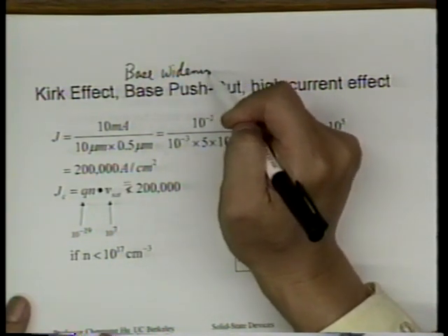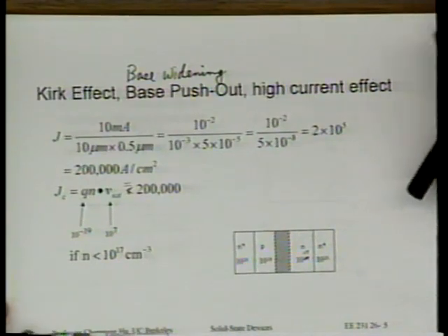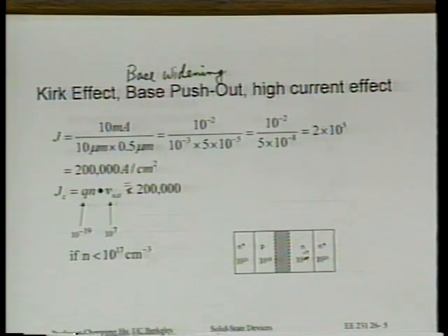And this is the thing that stands in the way between us and the 100 gigahertz bipolar transistor. Actually, the best silicon germanium transistor has an FT very close to that, maybe 90 gigahertz or something like that, but you cannot use it for 90 gigahertz application. Of course, you cannot design all the way to FT. So if we did not have this problem, we could have 300 gigahertz transistor just by pushing to even higher current density. Cannot right now, right?